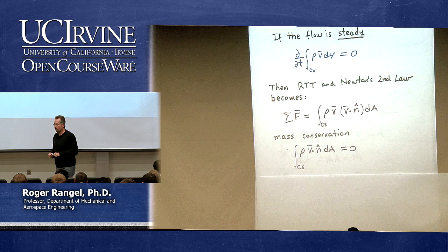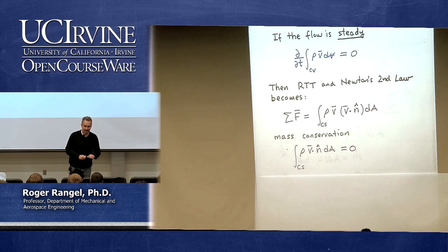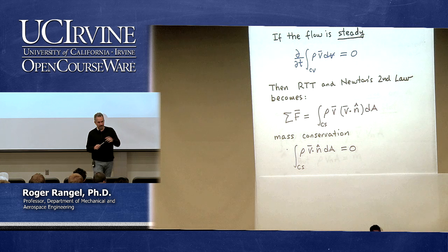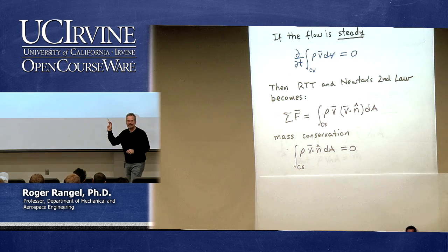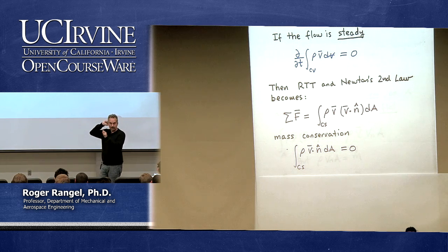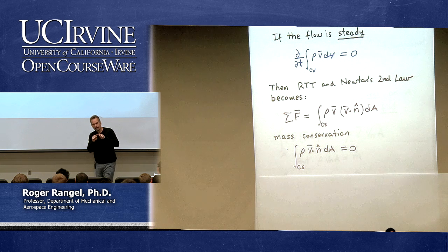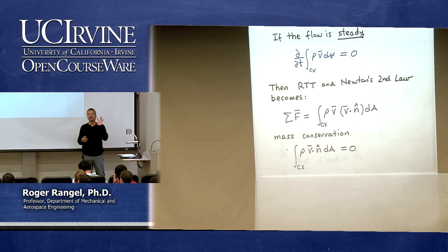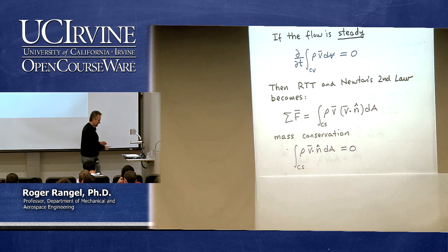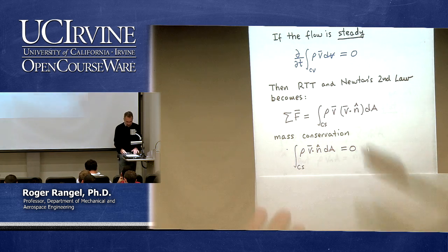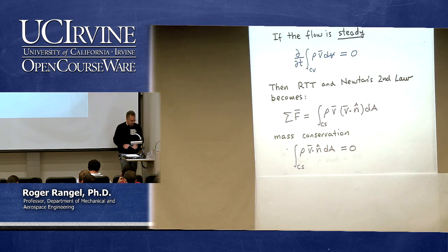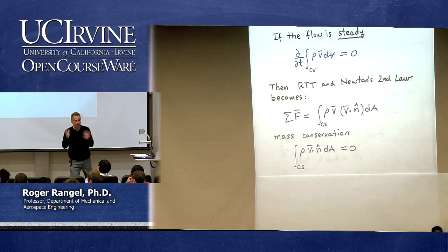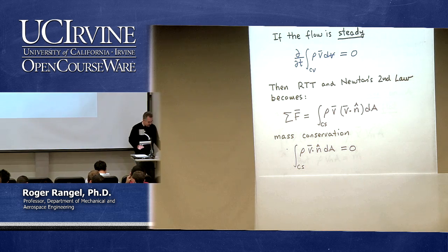Yeah, that's a very simple one. Flow of, what flow? Mass. It really says that the net mass flow rate out of the element is 0, because remember, that's what the term represents, the net flow out. Of course, net flow out is mass flow out minus mass flow in. So to say that the net mass flow rate out is 0 is equal to saying that the mass flow rate in is equal to the mass flow rate out. That's what this equation says. So in a problem, I usually have to deal with these two equations. Now let's put all of these simplifications together in one place and see what happens.